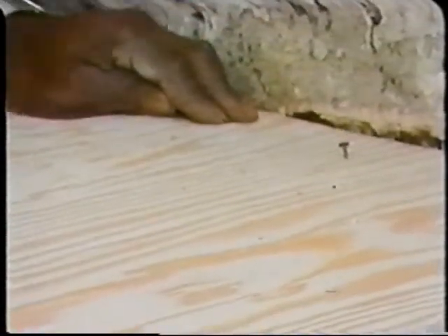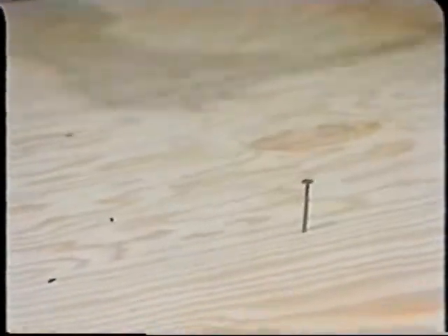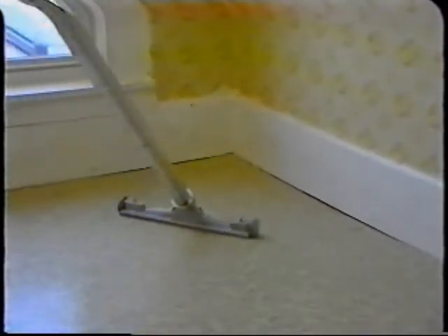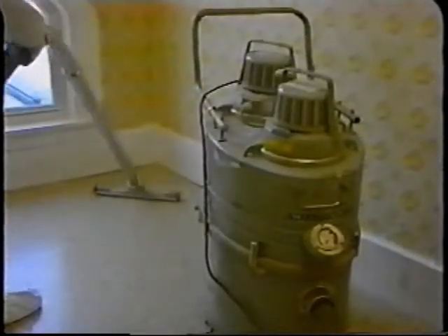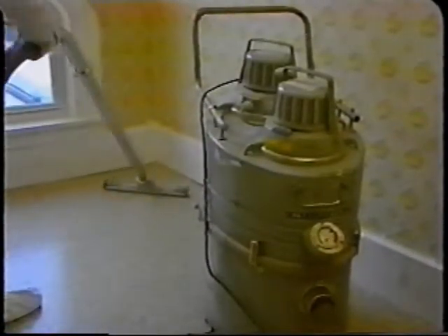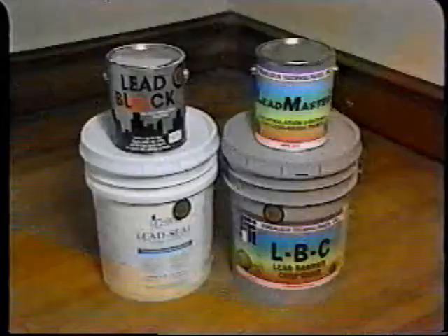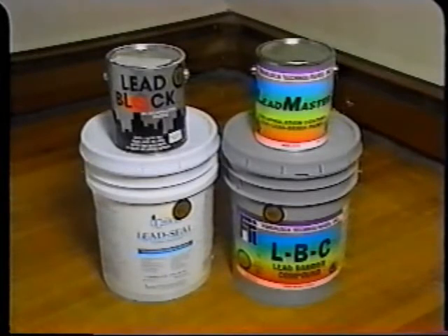If the floors are badly deteriorated, cracked, splintered, or have several gaps, it is necessary to take additional measures, such as laying new subflooring or covering them with tile or linoleum in order to assure that dust trapped within the cracks is not reintroduced into the environment. Tile and linoleum floors should be sealed through an application of common household floor wax. Concrete floors should be sealed with an appropriate sealant or paint.